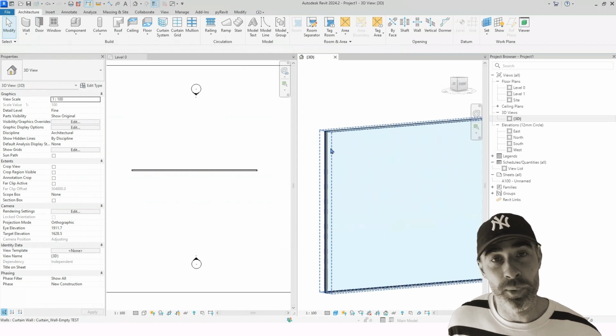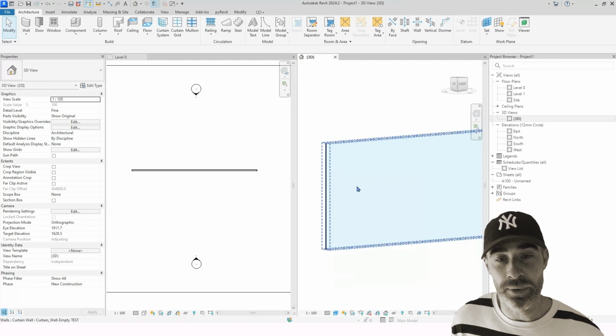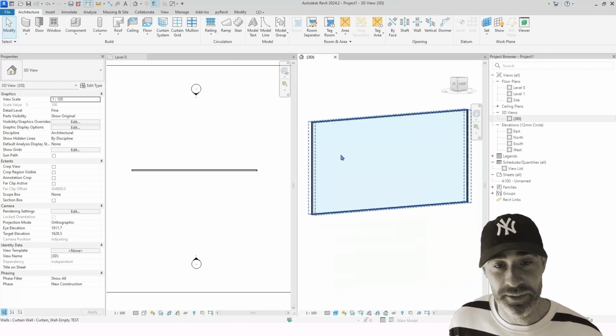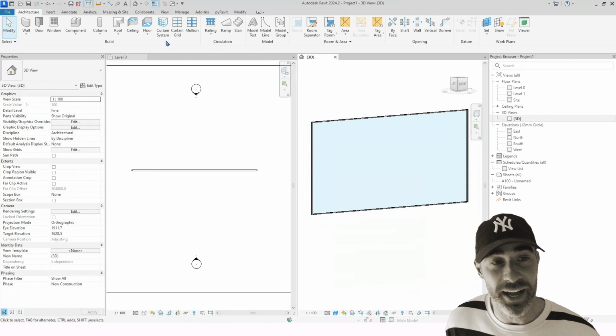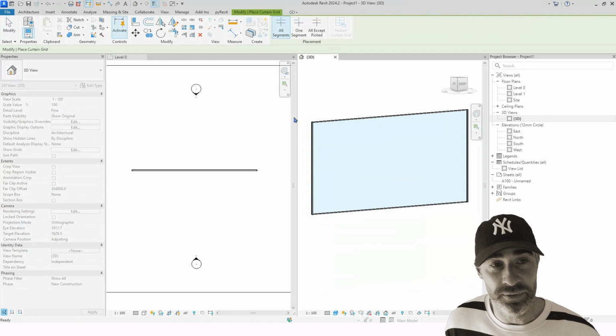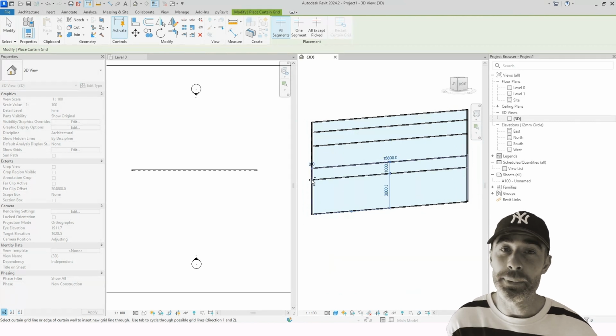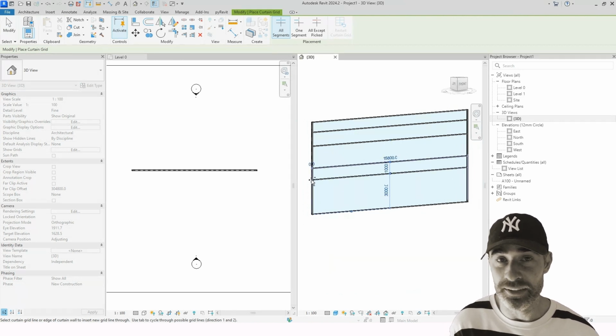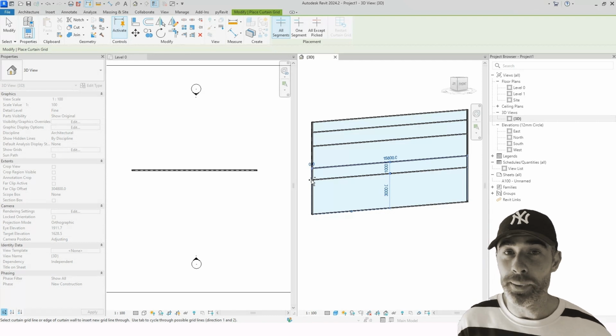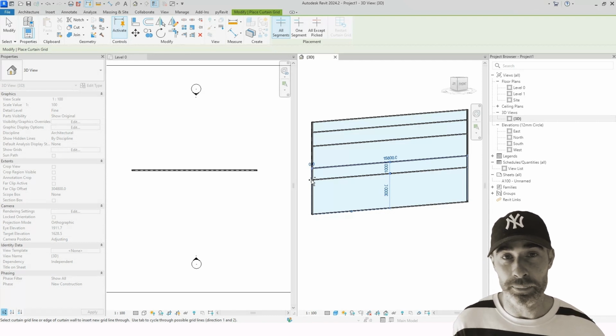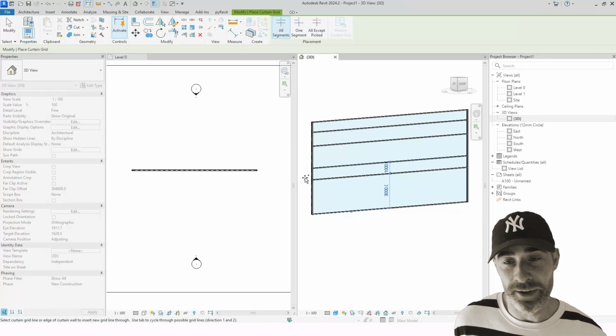I've got my border mullions assigned to this curtain wall, and I want to start to create something custom. And this is where in the architecture tab, under curtain grids, if you select this, I could start to place grids wherever I want. And keep in mind, your curtain wall already has those mullions. So as I create a grid, it's going to apply that mullion to that grid, which is amazing. It's what we want. If you don't want that, go back to edit your type and change that from your property. So as you create these, it's not automatically placing a mullion to your grid line.